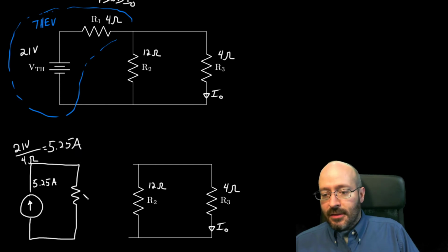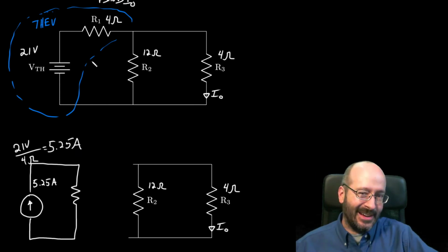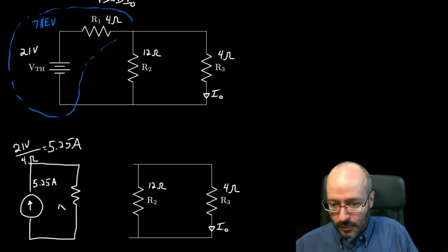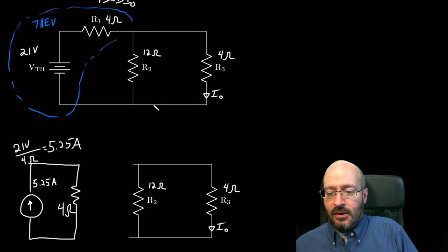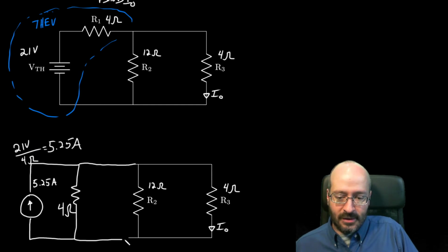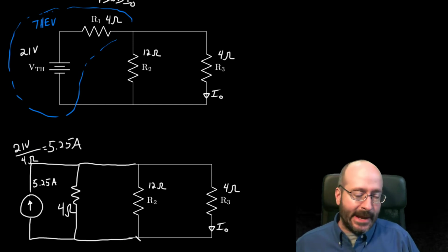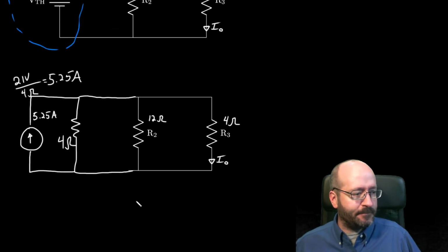Okay, the resistance, well, it just moves down. It's the same value, it's just connected differently. So it's still 4 ohms. I don't need to write a formula for that one. It's the same value. Okay, so that's the Norton equivalent of that Thevenin equivalent. And then I connect the load back to it. So the rest of the circuit, I usually redraw that by hand, but since we have it, might as well do a little cut and pasting, right?